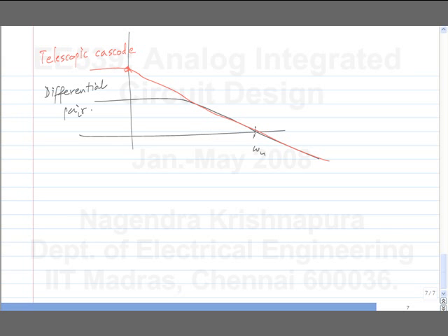Okay. If you wanted to improve the precision of your circuit, this is what you would do, right? You are not concerned about speed now. That's a different optimization altogether. Your DC gain was too small, so your precision was too small. The precision of the feedback network after it settles into steady state. So, then you have to increase the DC gain, and this is what you will have to do. Okay.